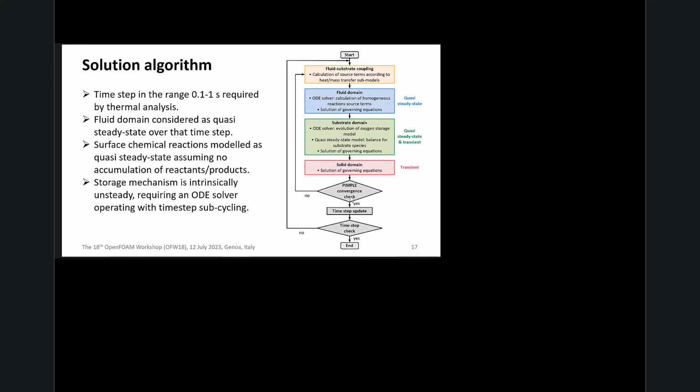We model with a quasi-steady state approach, and we use the time step that is required for the thermal analysis. For this reason, the fluid domain is considered quasi-steady over this time step. Also, the surface chemical reaction is modeled as quasi-steady, and we assume that there is no accumulation of reactants and products on the washcoat active sites.